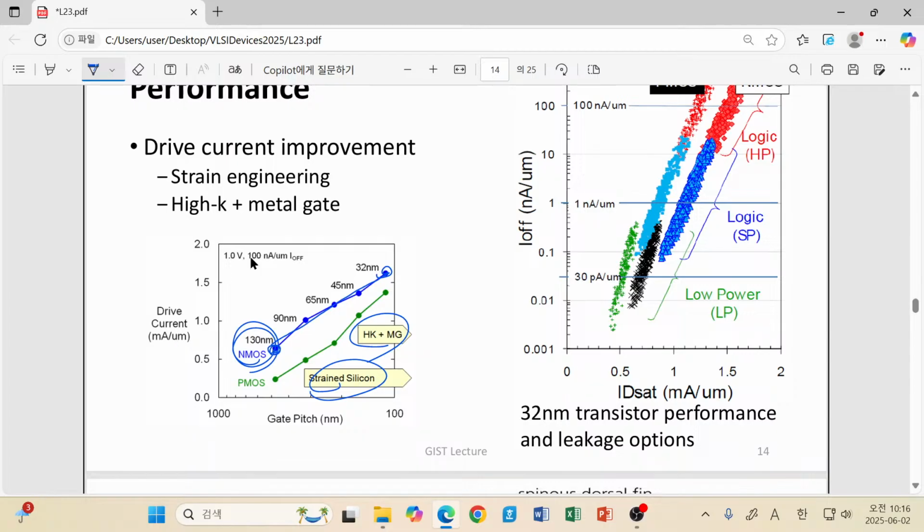So my final word is this. Please have a look at this number. You should remember the unit scale, milliampere per micrometer, or sometimes microampere per nanometer. They are the same, just a 10 times scale difference. In this case, a state of the art device should have some numbers like 1, 2, 3. So please check whether your own device has such a large number. There are not many technologies which can achieve this number.